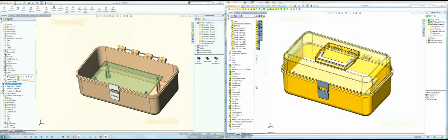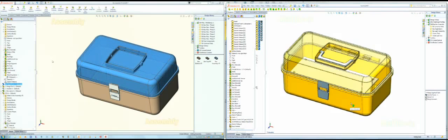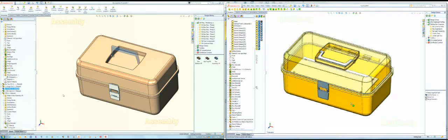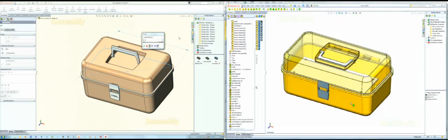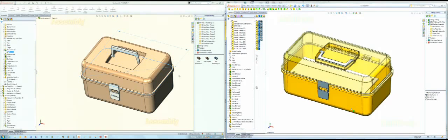So we probably need to see the top of the box before we do that. And we should probably show the handle. Okay, so there's the whole box. So how do I change the size of the box? Well, hopefully that's all controlled by that very first sketch. If I want to make the box a little smaller, let's see, the circuit board got 1.5 inches smaller, so let's just take the box down to 10.5 inches and rebuild it. And if all goes well, the top follows it.